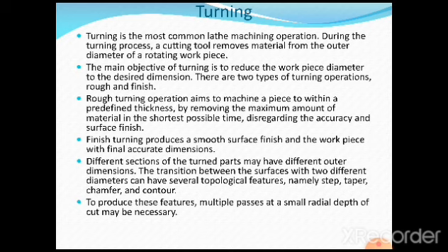Because when we are going to touch the final dimension of 20 millimeters, the depth of cut which we give is less compared to the beginning of the operation.